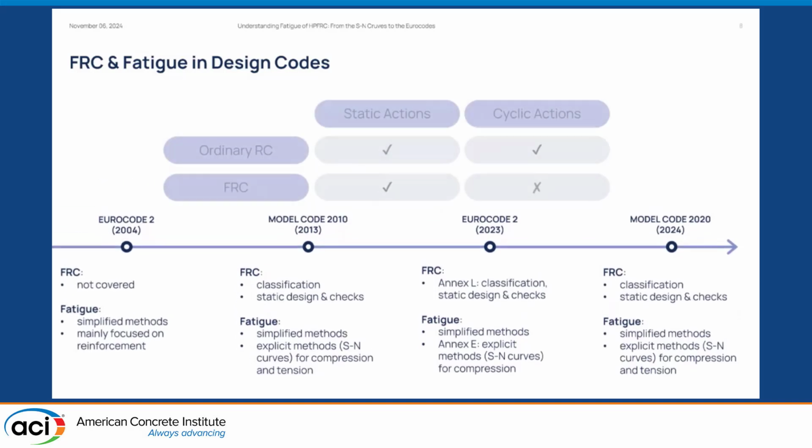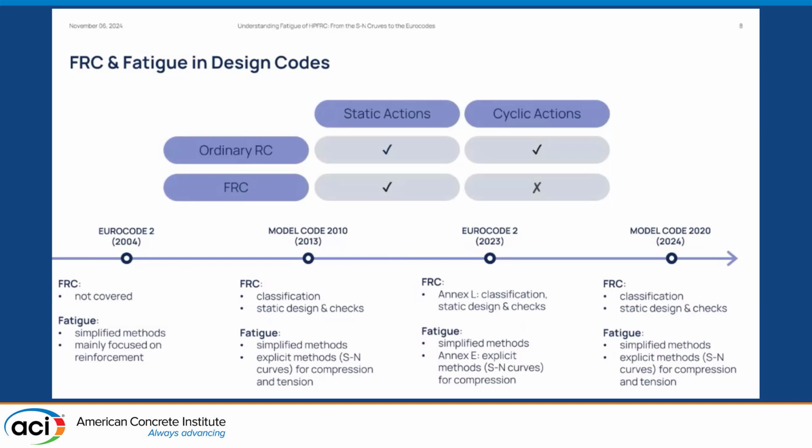So the thing is that we currently have design rules and checks for static action, and cyclic actions for ordinary reinforced concrete, but coming to FRC, there are no clear rules nowadays for cyclic actions, and this may hinder the possibility of using this material, which is very promising, as it has been shown, and also has enhanced capabilities, of course.